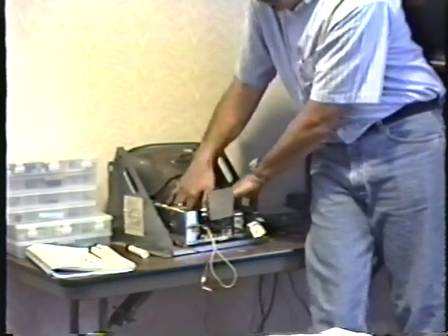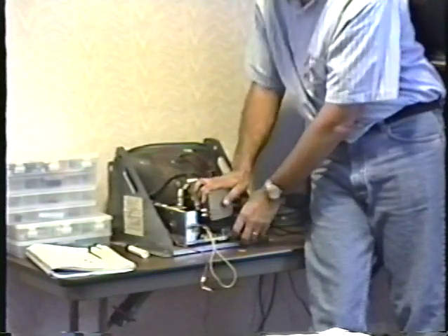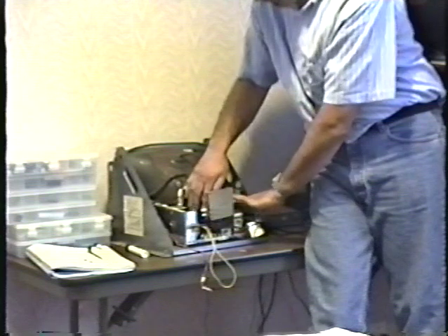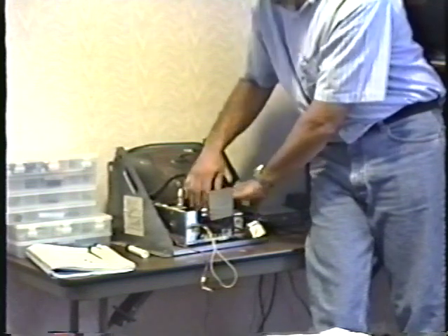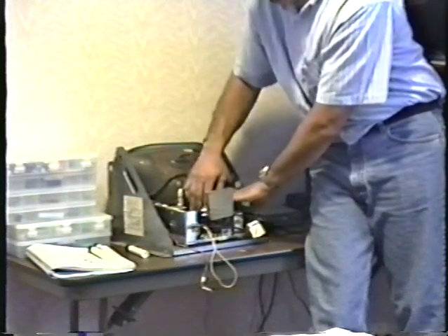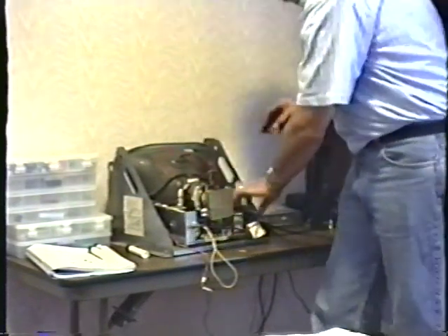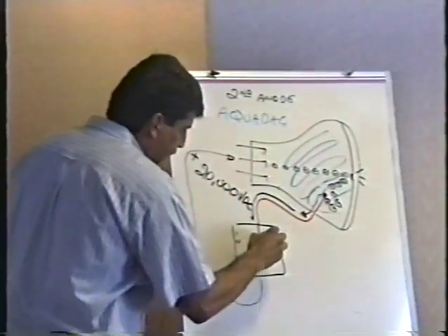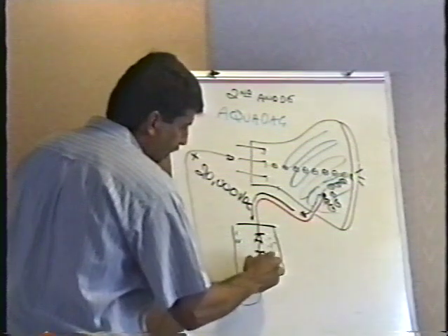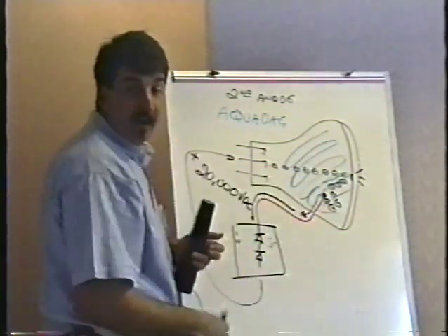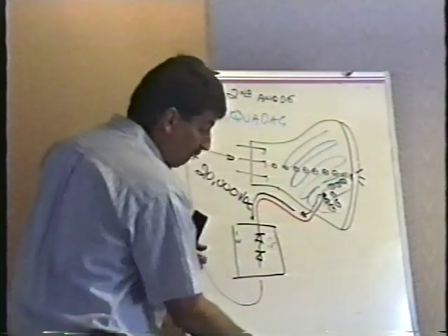Even though the picture tube is probably fully charged right now, it is impossible for that charge to get out of the picture tube and to anything else on the monitor. Because in the high voltage unit, there are some diodes, and the diodes are facing this direction. Well, a diode's a one-way gate. There's no way for that electric current to get out of the picture tube to anything else on the monitor.